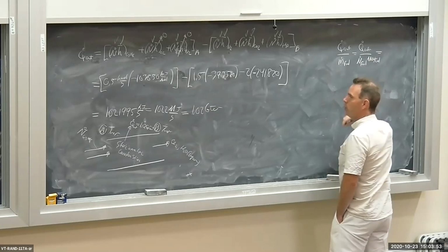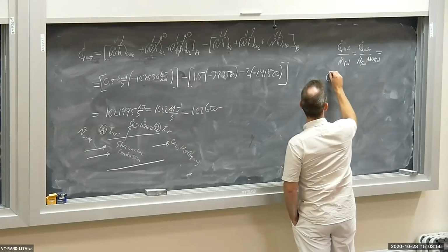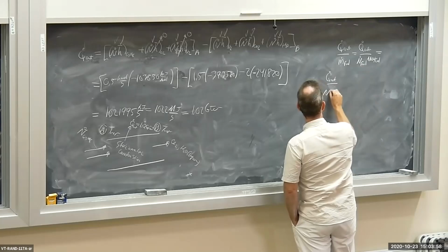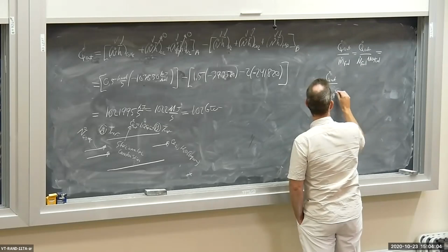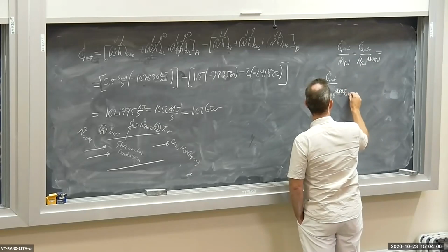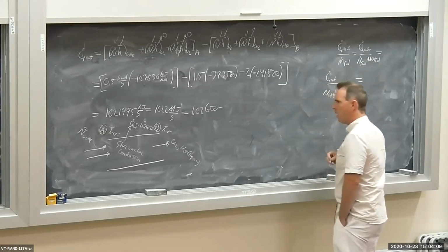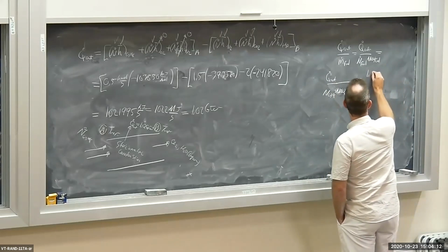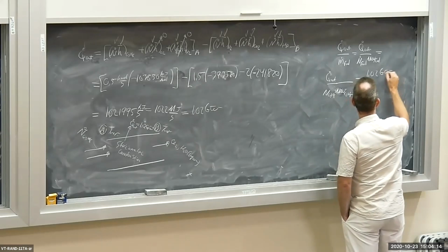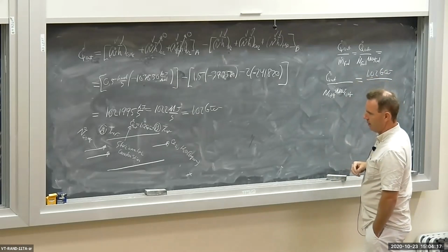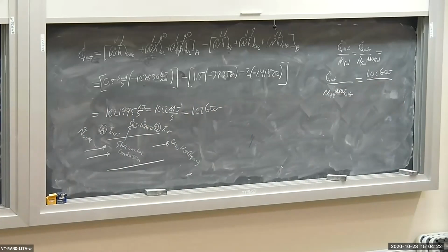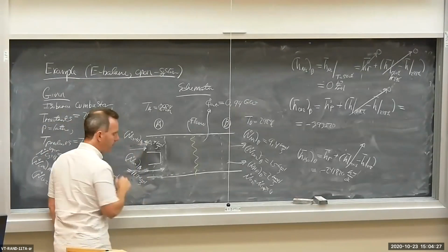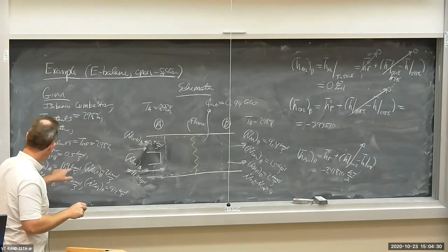In our case, this is propane. So this is going to be Q dot out, N dot C3H8, molecular weight of the C3H8. Let's see here, I get 1.02 gigawatts. My N dot for the fuel, well, that was 0.5, so half a kilomole per second.